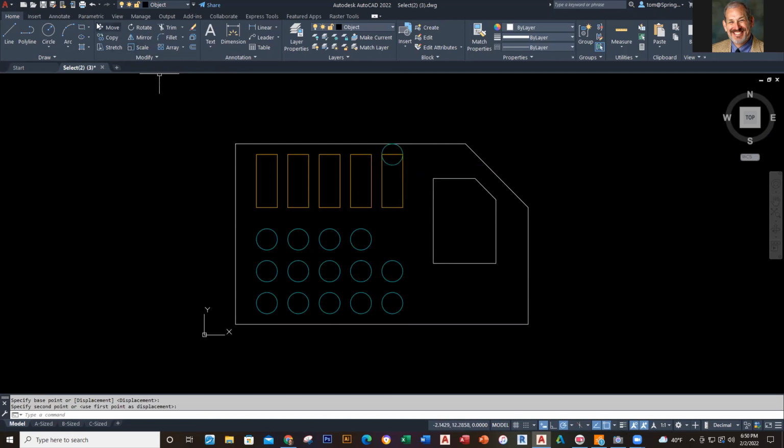And I'm going to repeat that. So I go to move again. I click on move and I click here. I right click and I go here and I move this up. This is the select drawing. So I'm going to repeat this again. And when it asks me to select the objects, I click on the object. To tell AutoCAD I'm done, I right click. The base point, best thing to use is the center of the circle.